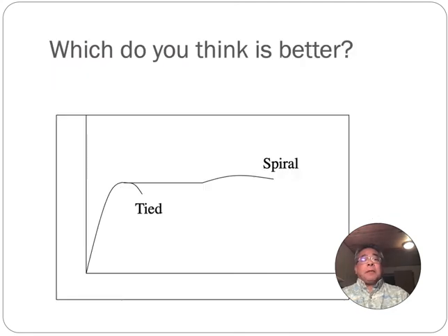And while they have about the same strength, the key advantage, as shown in this schematic graph here, is that the spiral columns can deform much, much more. And this is particularly important for seismic response. This is really important: the drift capacity of the piles.